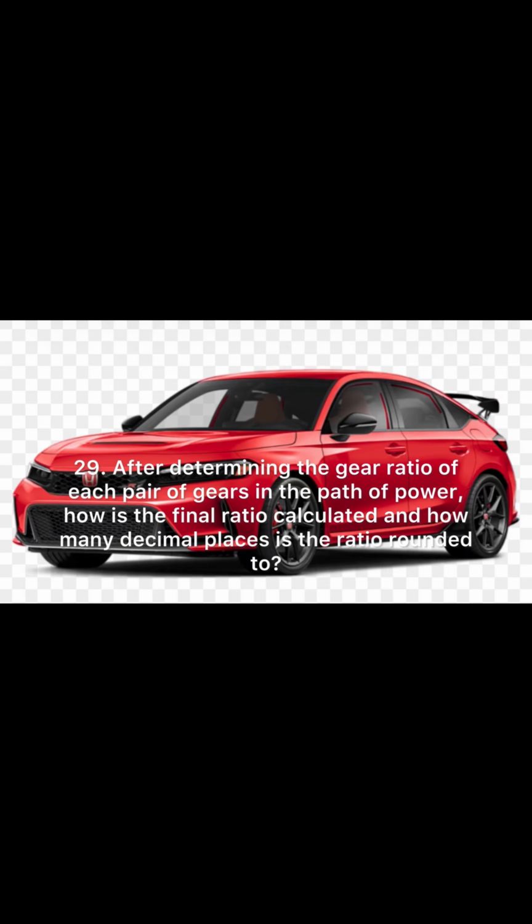Objective for lubrication. 30. What are the 4 purposes of lubrication? Reduce friction, cool, clean and seal. 31. What are the three most common lubricants used in manual transmissions? Gear oil, automatic transmission fluid or engine oil. 32. What component in a manual transmission acts as the pump? Cluster or countershaft.